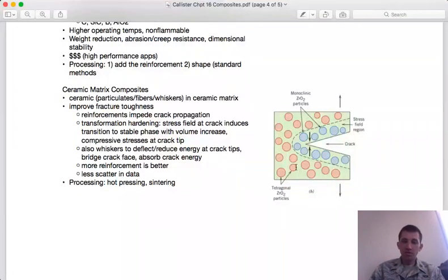So if you look at their phase diagram, as a function of pressure and temperature, you've got regions of these two phases, and what happens is you have the particles in the material normally in one phase, and as a crack is propagating, it is putting these particles under compressive stress. And this shifts the point in the phase diagram, and if it shifts it into a region where there's a phase change, that compressive stress can actually initiate a phase change in these particles.